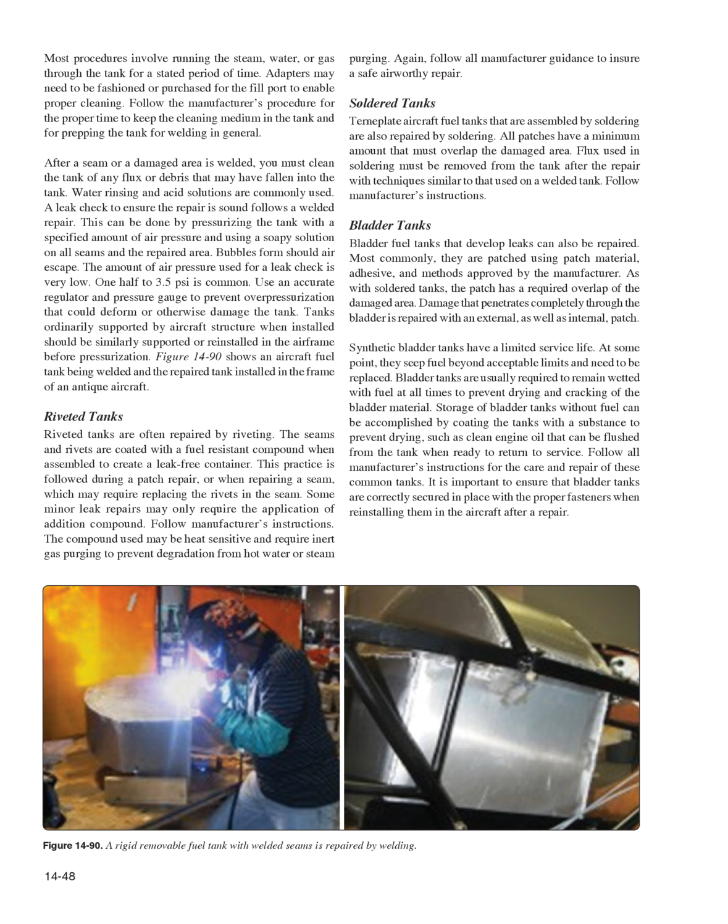Follow manufacturer's instructions. The compound used may be heat-sensitive and require inert gas purging to prevent degradation from hot water or steam purging. Again, follow all manufacturer guidance to ensure a safe, airworthy repair. Soldered tanks. Aircraft fuel tanks that are assembled by soldering are also repaired by soldering. All patches have a minimum amount that must overlap the damaged area. Flux used in soldering must be removed from the tank after the repair with techniques similar to that used on a welded tank. Follow manufacturer's instructions.